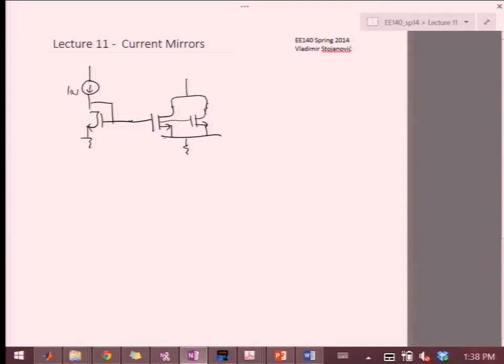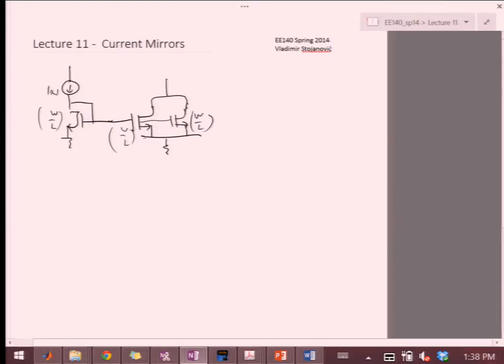Right? So all of these have some fixed W over L. In fact, in modern design, you actually do a lot of these on the sides as well, so that only the ones in the middle are kind of not stressed and well matched. And so that's how you ensure that the multiplication here is exactly some integer amount. Okay.